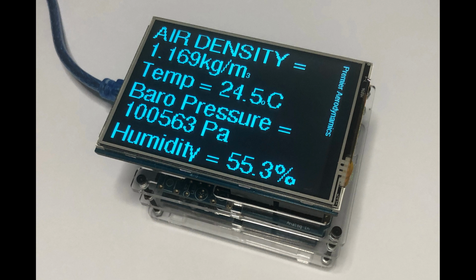In that particular case, it actually led to a 10% change in the drag coefficient. It was 9.5%, I think, because the flow physics was different, and the lift was about a 2% change in that particular case. So that's why you want to measure the density accurately, and that's one case study that I just threw out there to show you what can happen if you don't.